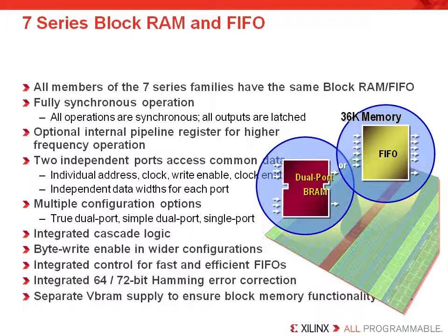You should also be aware that the 7 Series FPGAs require a separate power supply to power the block RAMs. Now that feature is different from the Virtex 6 device family. Now this ensures proper operation if you're targeting the -1L speed grade of the 7 Series product family.